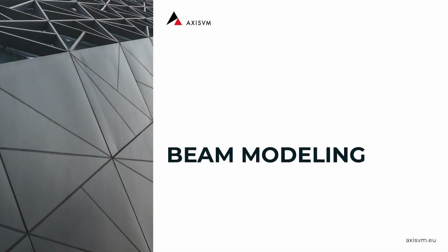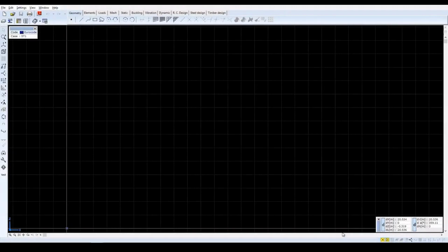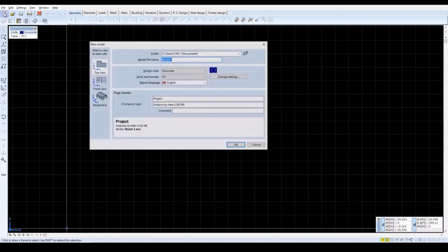Welcome to the AXISVM beam modeling and design tutorial in accordance with Eurocode 2. Once you have opened the program, create a new model by clicking on the New icon. In the dialog window, replace Model File Name with Beam. Select Eurocode from the design codes and set the units and formats to EU.